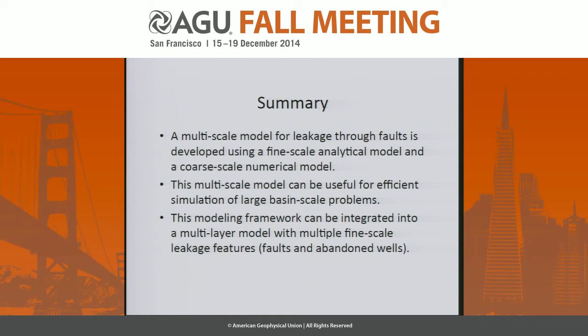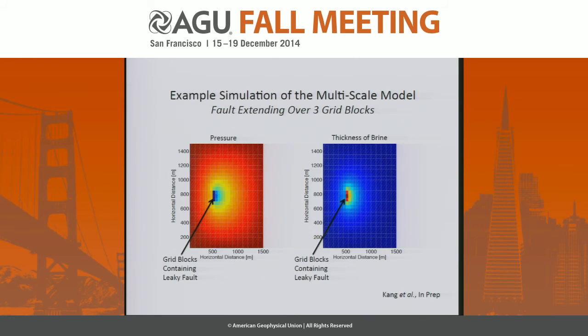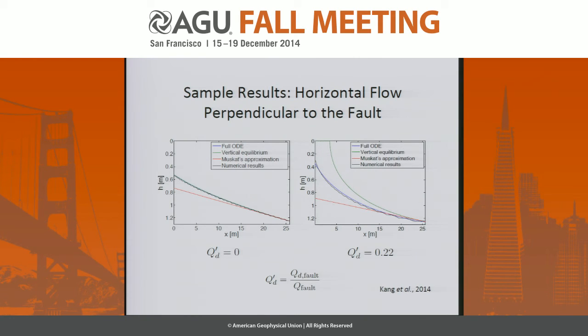I wonder if the vertical equilibrium model assumption is valid for multi-layer medium. So in the fine scale, what we found, which is what I showed in the one paper, is that the vertical equilibrium assumption, you need to relax it, and that's one of the results I show here, right? So when you have two-phase leakage, it depends on your domain, how long your aquifer is, the thickness, and you can determine whether it's applicable. But for the core scale numerical model, it should be okay, especially if you have thin information.